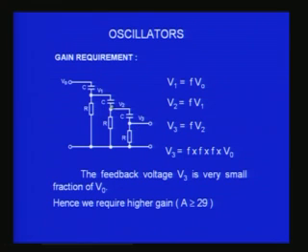Therefore the value of R will be affected by these two because they are in parallel combination. Again this R is affected by these RC, etc., and therefore you would not get the same R in each of the stages because of the presence of the other components, and therefore they will never be equal to 60 degrees. You will get almost close to 60 degrees if you observe, but it is not equal to 60 degrees.